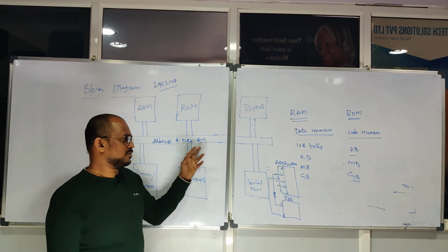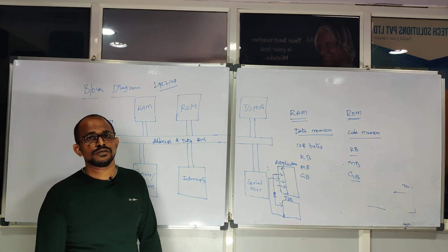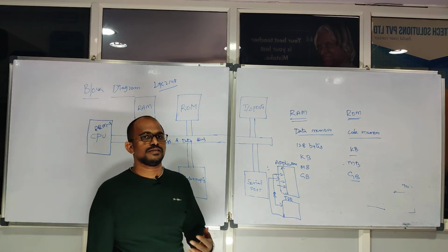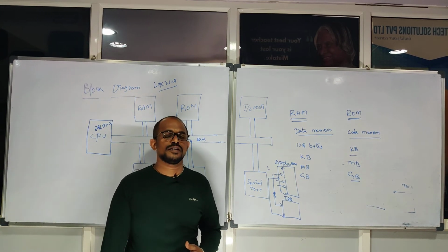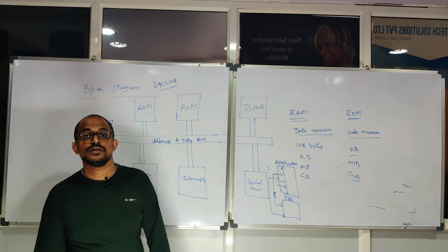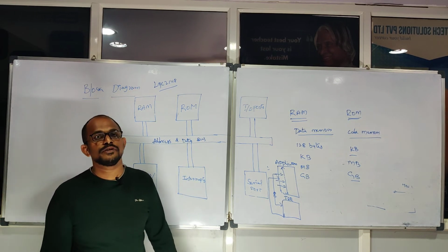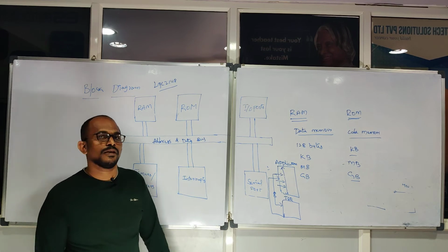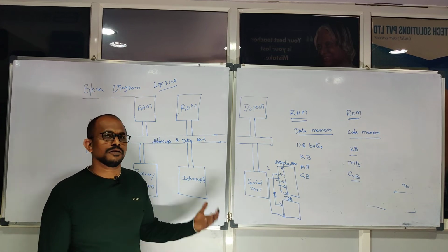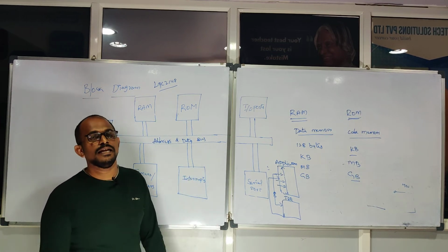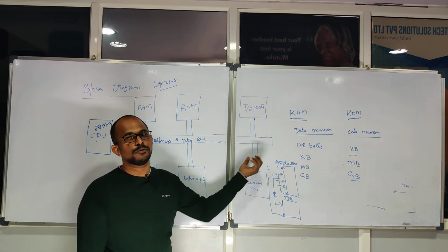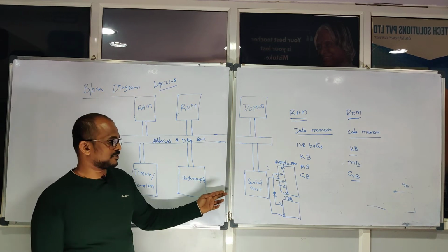These interrupts are supported by all microcontrollers, but basic microcontrollers have a limited number of interrupts, like 3, 5, or 6. If you move to 32-bit generation controllers, the number of interrupts is higher, maybe 10 or 30. So you have more flexibility with interrupts and can do more priority tasks in your application. Interrupts are very important for pharma and medical products. They are highly used for such applications, but in regular applications you can manage with regular IO port programming or a regular process.